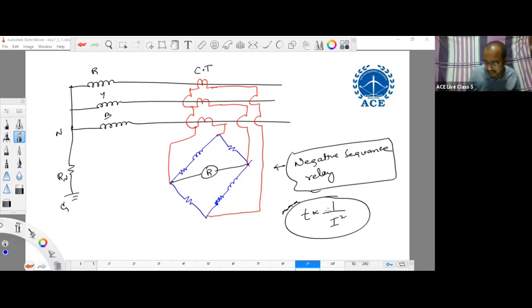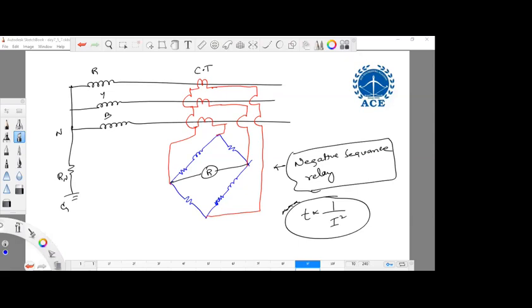That's why I have set the earth relay to 10 to 20%. Okay. So getting exact balance is difficult, sir, because loads are continuously varying, no? Yes. Getting exact balance is difficult. That's why even if there is variation around 10 to 20%, we treat the system as balanced, and we will go for balanced calculations.